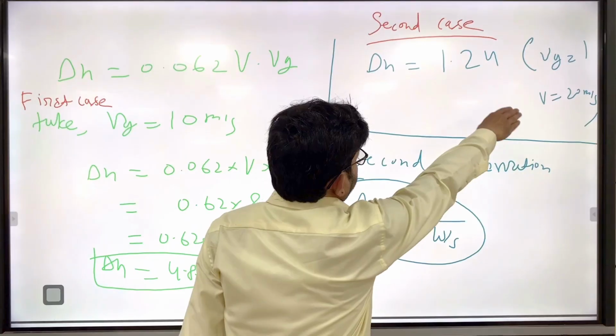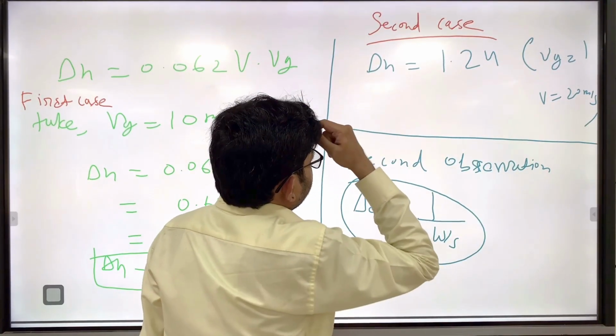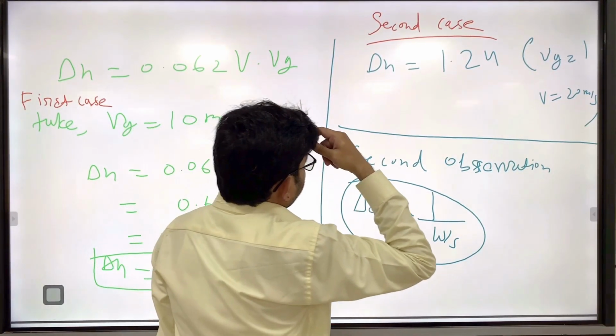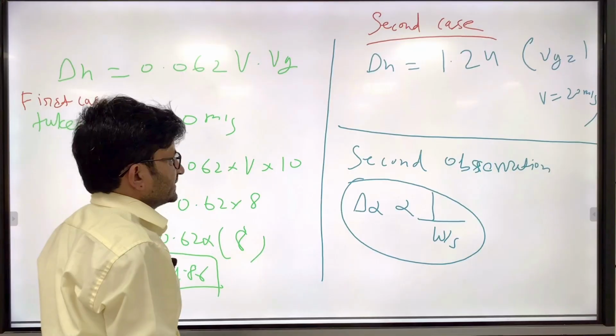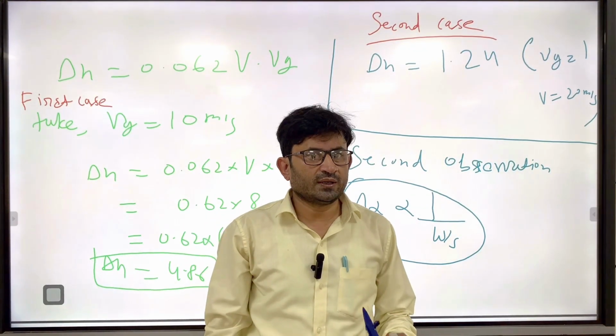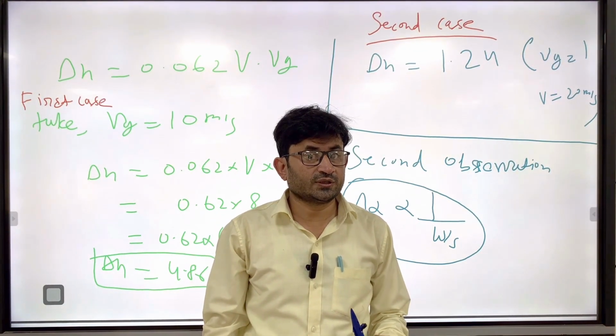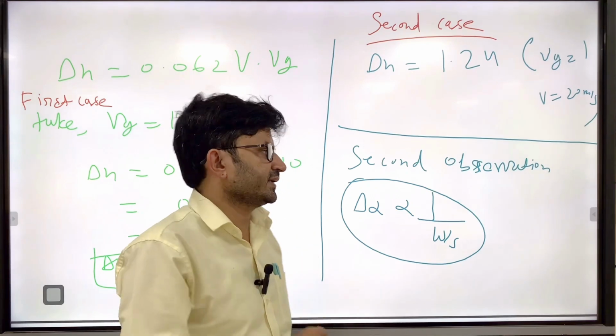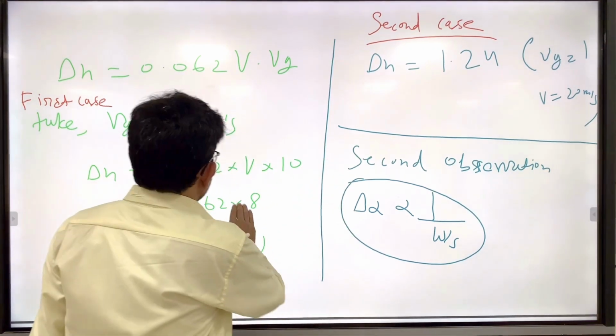And let's say if you are flying at 20 meters per second, but the gust is 1 meter per second, so delta n will be 1.24. So if you are flying at 1, 1 plus 1.24 becomes 2.24. You will be inside the envelope if you have an nmax of 3, let's say.